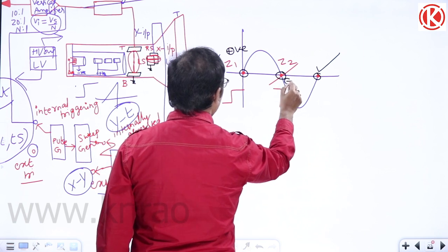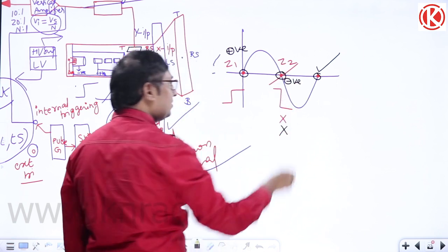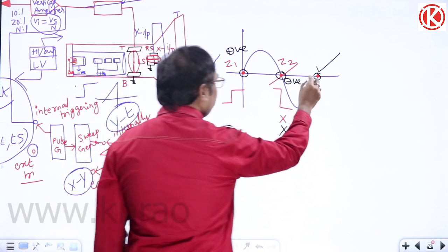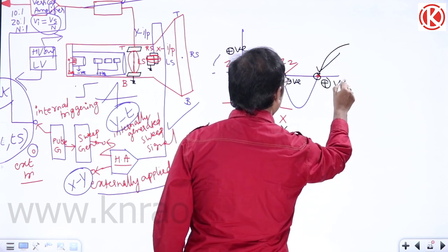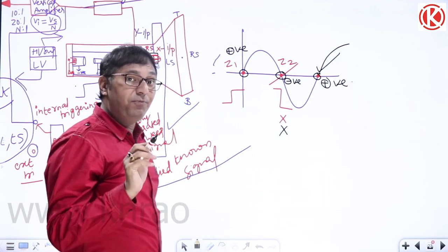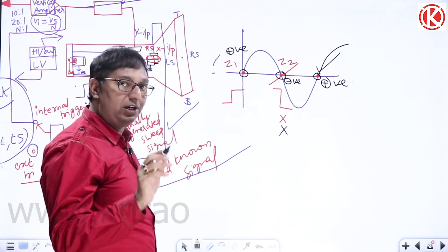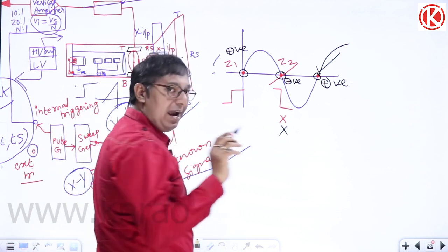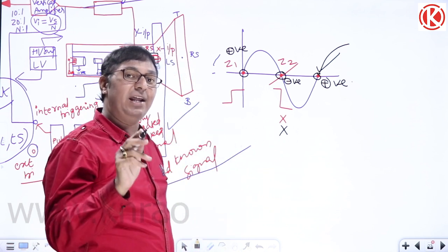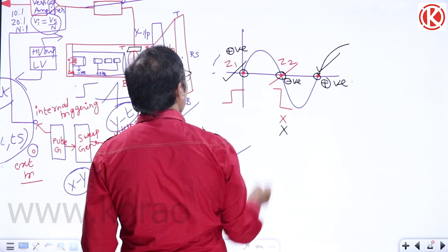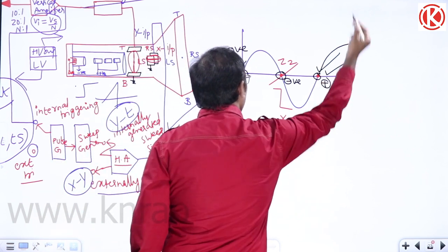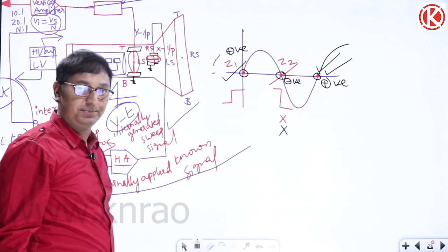At this point, the waveform is falling, the slope is negative. At this point, again the waveform continues, the slope is positive. If we can set triggering voltage level as 0, and if we can set triggering slope is positive, at this point the start pulse is produced, at this point the stop pulse will be produced.